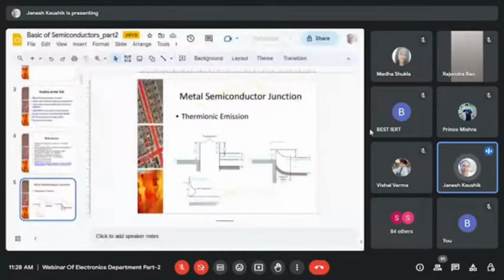And here thermionic emission, I have discussed that theory is applicable to calculate the currents across this barrier. When we forward bias it, that barrier is reduced and more electrons can flow, and the forward diode current is exponentially related to the applied voltage. In reverse bias, there is a leakage current, almost constant, but it is again related to the barrier of that metal semiconductor junction.